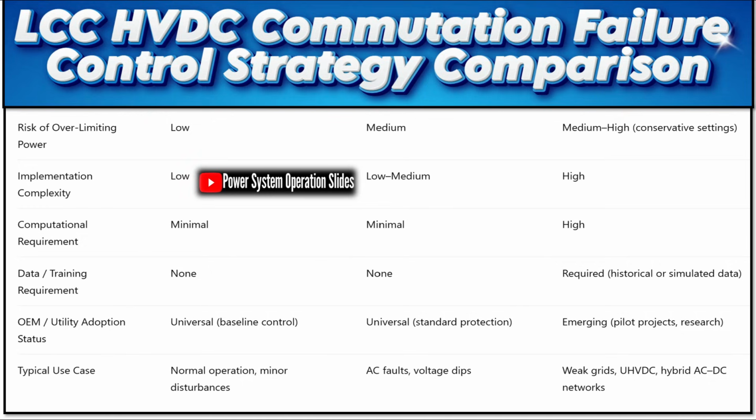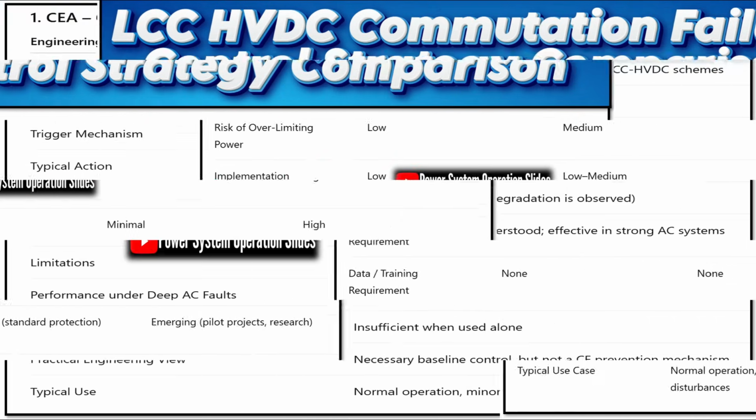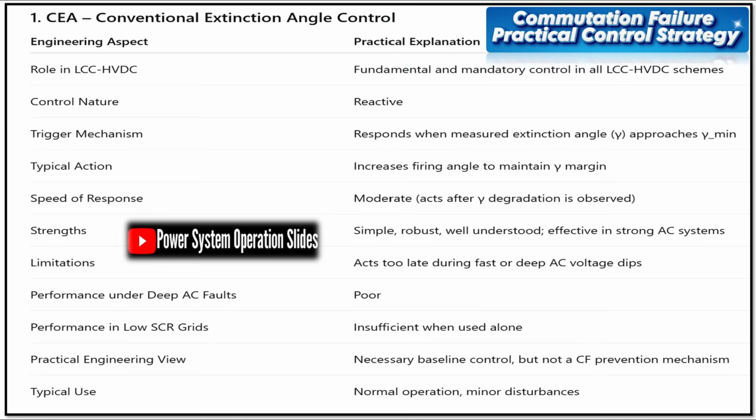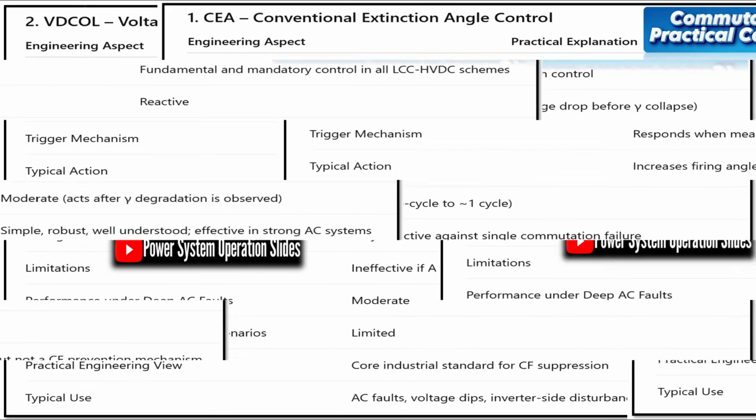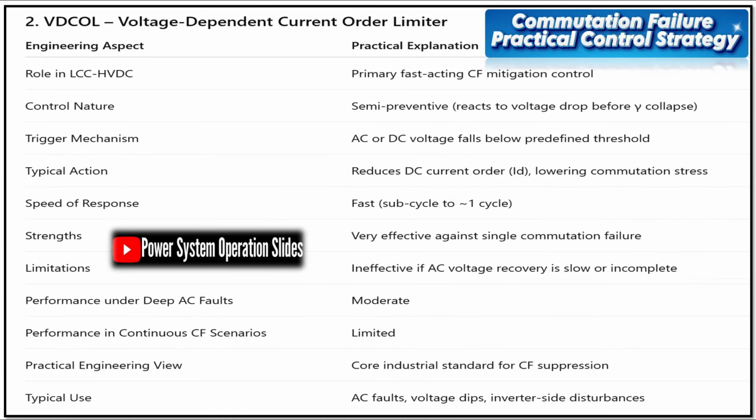Special attention must be paid to systems characterized by strong DC and weak AC configurations, where the electrical distance between HVDC landings significantly impacts system behavior. The China Southern Power Grid's approach to AC-DC protection coordination, which optimized 5 DC protection functions and validated them through extensive simulation testing, demonstrates the effectiveness of coordinated protection strategies.